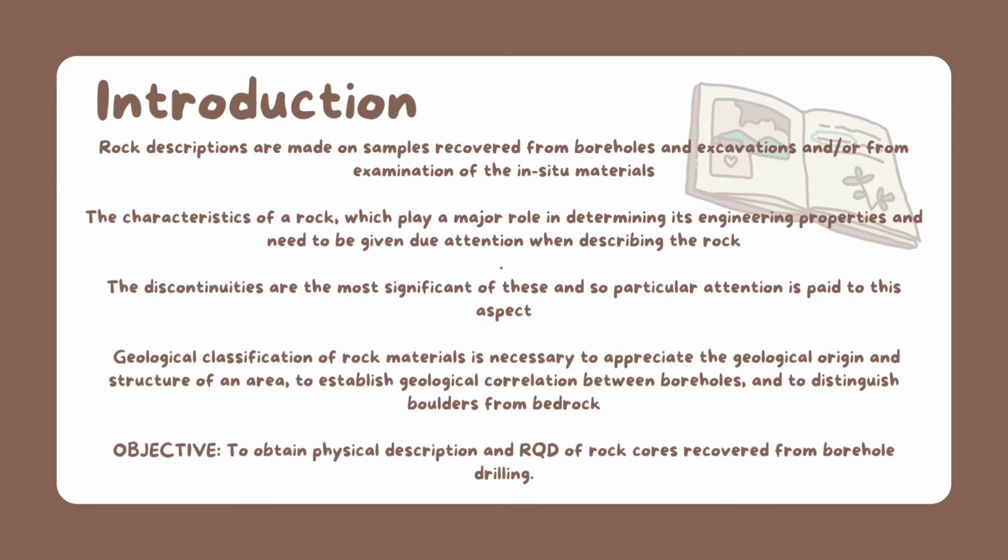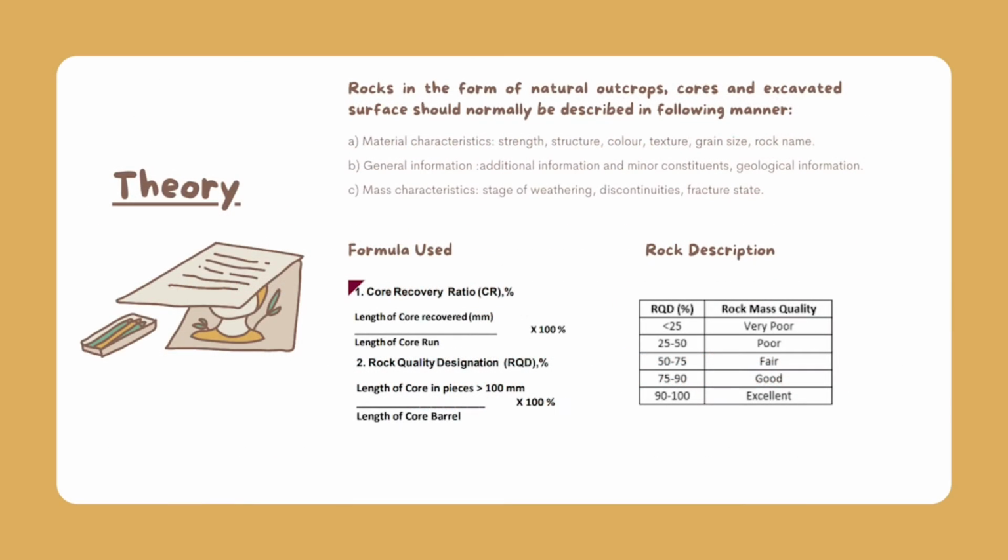Geological classification of rock materials is necessary to appreciate the geological origin and structure of an area, to establish geological correlation between boreholes, and to distinguish boulders from bedrock. Our objective is to obtain physical description and RQD of rock cores recovered from borehole drilling. Next, I will present the theory of this experiment.